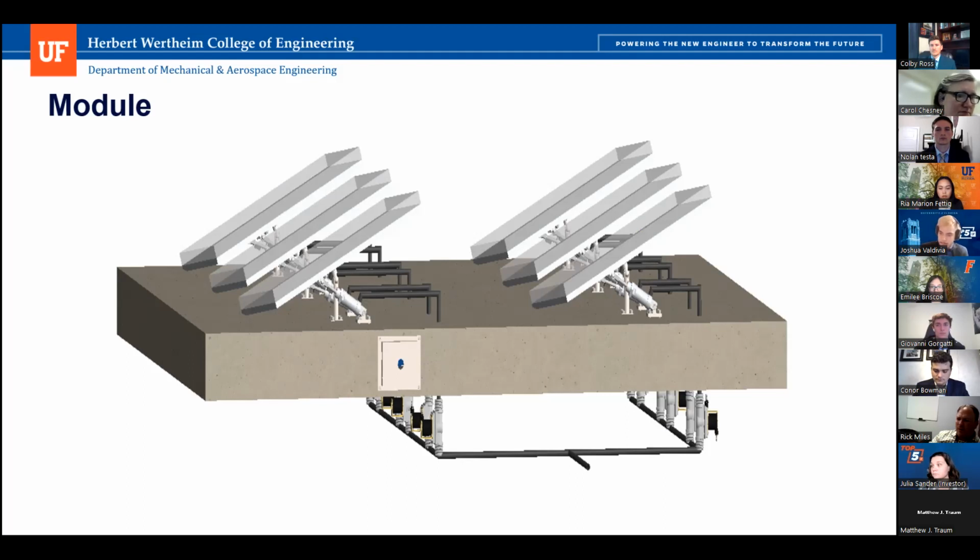Okay, and then when you're dealing with hydraulics and pneumatics, typically you're going to have to set some sort of servicing schedule based on how much they're being actuated and that sort of thing. So just something you're probably going to need to consider is how you're going to go about servicing the pumps, because you're going to have them break down from time to time. Solenoids tend to be sticky a lot of times, so just some concerns that you might have down the line from a maintenance standpoint.